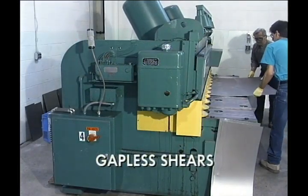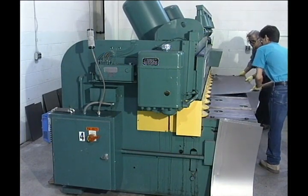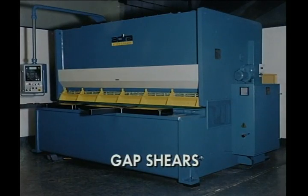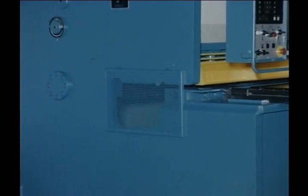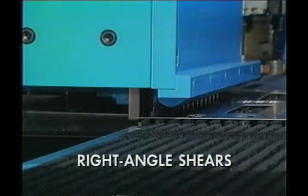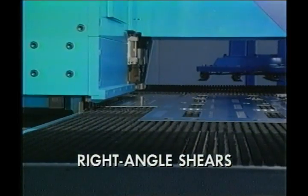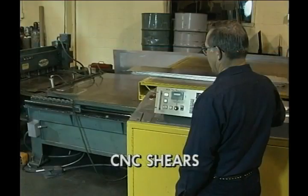Gapless shears have side frames which support the power unit and are joined together by the bed and crosshead. Gap shears are used for squaring sheet stock and producing blanks. Because of the gap or throat opening in the sides of the frame, they can handle larger sheet lengths than a gapless shear. Right-angle shears employ two sets of dual blades set at a right angle for simultaneous cuts along two axes.